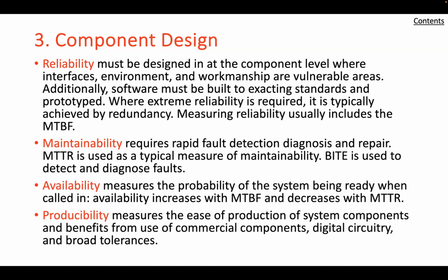So next, let's talk about risk management, and this will be the final topic here. Many of the methods of risk mitigation listed in another chapter, and we talked about in detail before, are pertinent to the component design step in the engineering design component. Components containing residual risk factors must be subjected to special technical and management oversight, including analysis and testing to ensure the early discovery and resolution of any design problems.